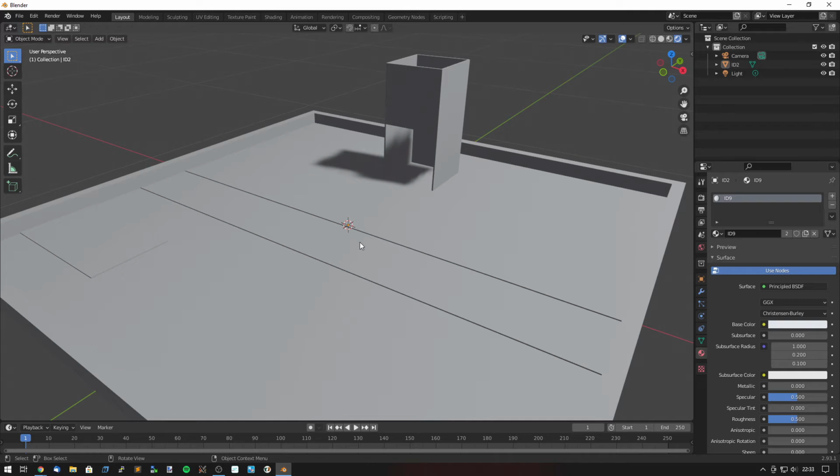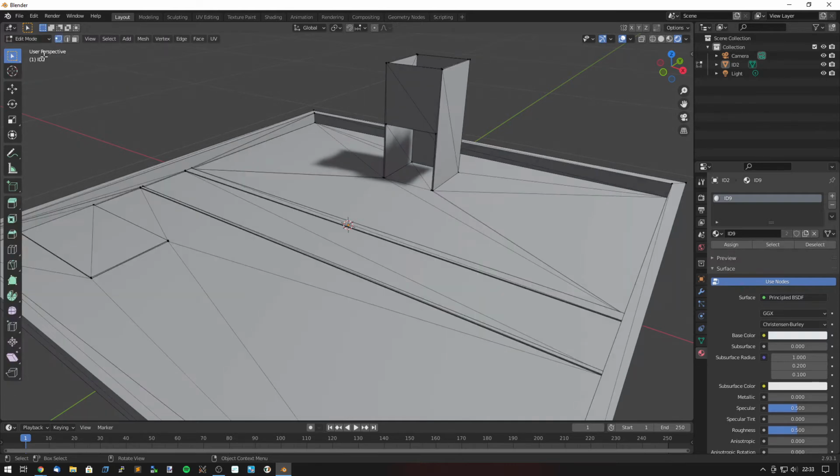Right, so what we want to do is select individual parts of this model, and if I click on here, it's always just going to select the entire object. So I want to be able to edit part of this, and we can do that by changing the object mode. I'm going to unselect it, drop down that object mode up here and go to edit mode. There we can see the triangles, and little dots on the edges, the nodes of these triangles where all the triangles link to.